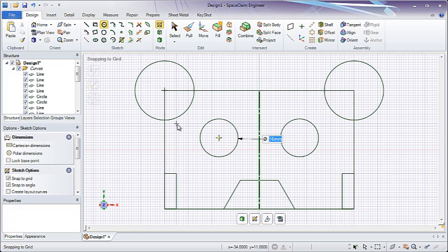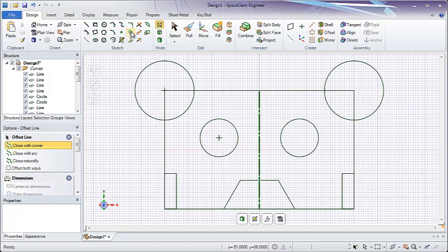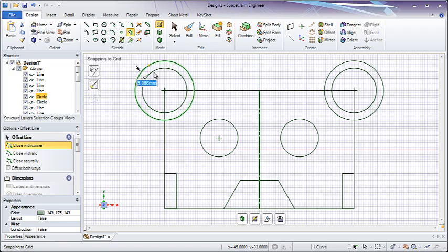The last thing for me to do is to modify this. Remember, the tools on the left will create new things in your sketch, and the tools on the right will modify your sketches. For example, let's say we want to offset some of these curves. I'll click on our Offset button and choose this circle. Remember, because the mirror line is still on, if I offset this line, it's offset on the other side as well. I'm going to type in 4 millimeters to create that offset.